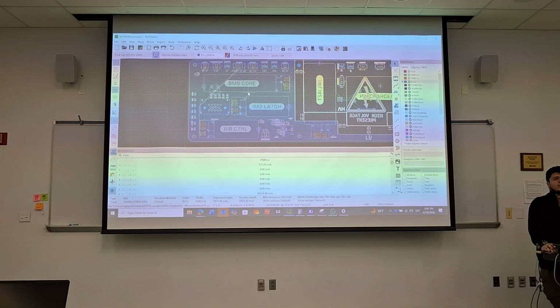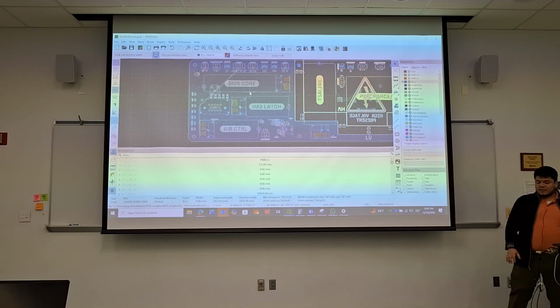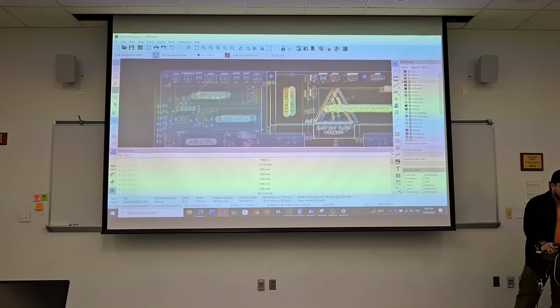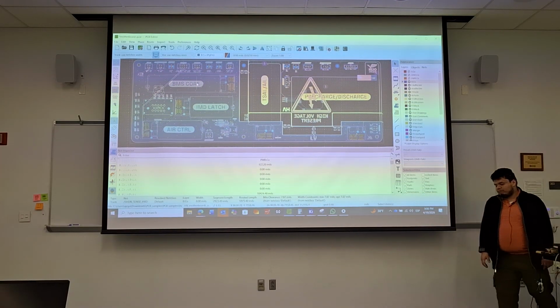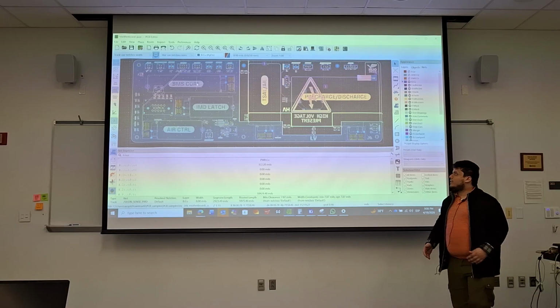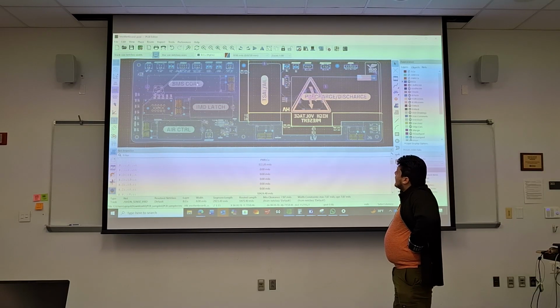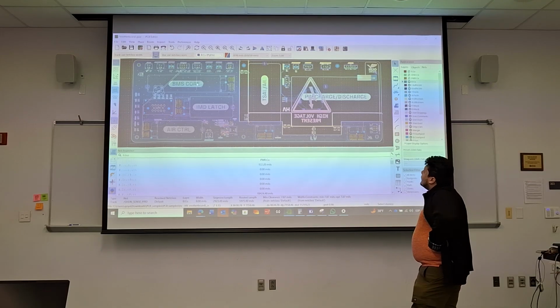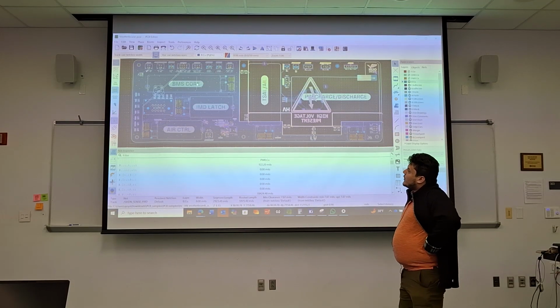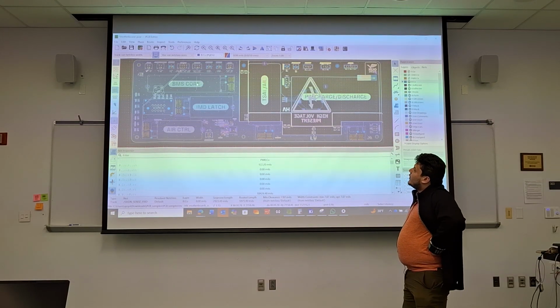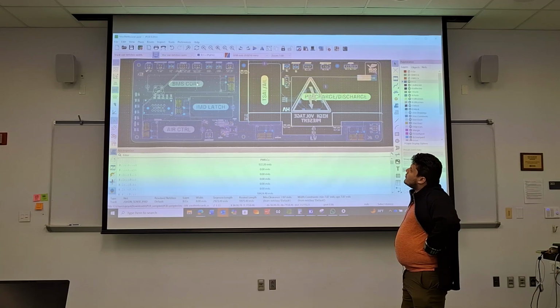I think an 8-layer board might be okay for this, simply because you have so much going on. Something to consider. Because it's so big, it would get very expensive. So maybe it might be worth getting another revision on this where we do a little bit more shielding before we crank up all the layers.